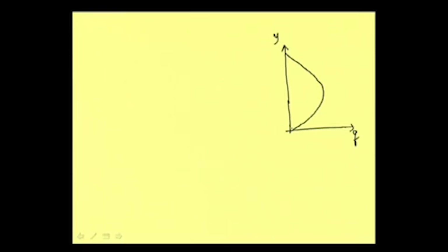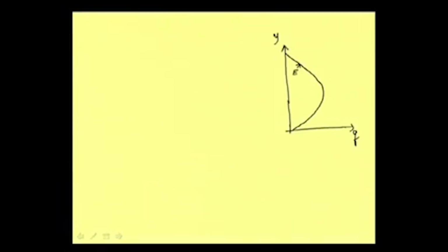It is coming like this. This is the depth discharge diagram, and this line we are getting for a particular energy level E. Say this is for specific energy E. Along this line our energy is remaining the same. When energy remains the same, then with the increase of depth, discharge is changing, or we can say when unit discharge is changing, then depth is changing.